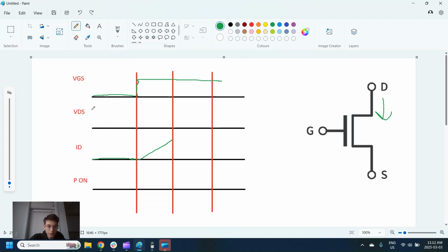And we see here that the voltage actually in this time stays constant. So as the current is increasing, the voltage here actually stays constant, meaning you need to maintain that voltage to ramp the current all the way up, and then that voltage can start to come down. And again, that voltage does not come down instantaneously. That voltage takes some time to come down, and it's going to ramp down linearly as well between this middle time here and our total end. And during this time, the current has maintained its constant value, which is its full current. And then the voltage will drop to some very, very low value, which we approximate to 0.